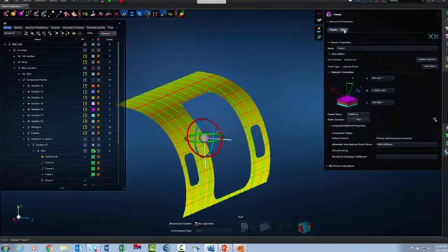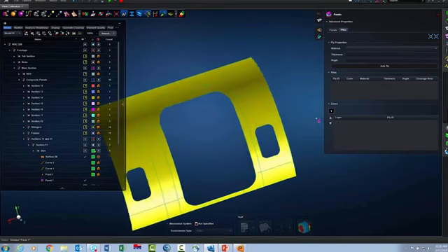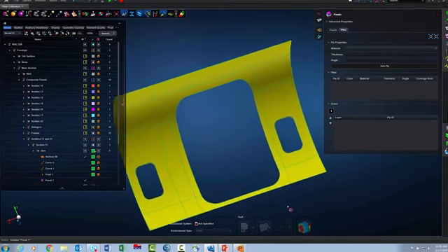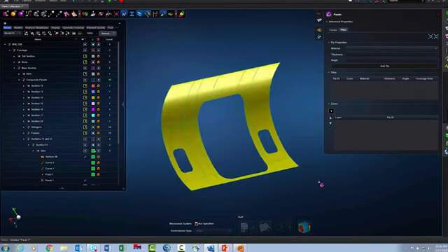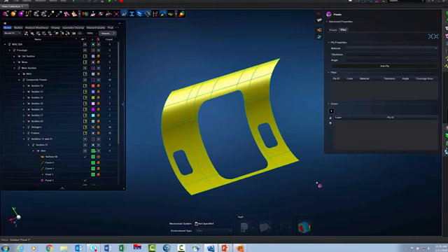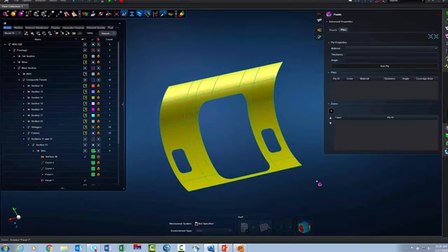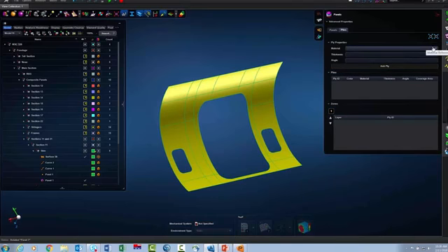And now let's start laying some plies. Let's look at what it's like to lay up a laminate using the composite panel in Apex. I'm going to turn my surface around because, remember, I'm laying them from the inside out, so I just want to keep in sync visually with what's happening there. And let's start laying some plies.